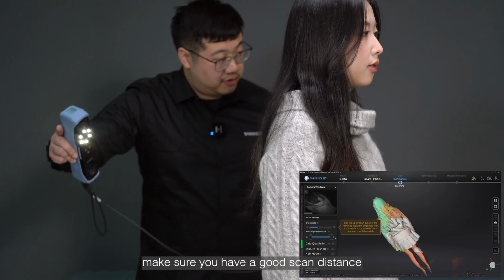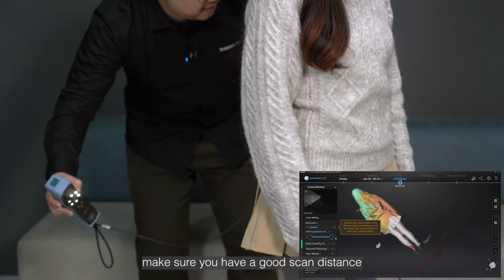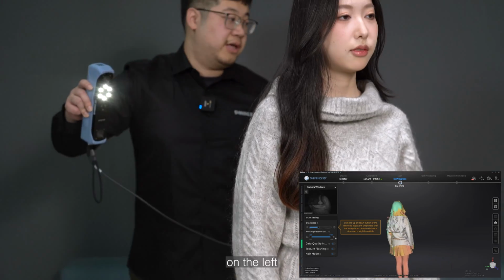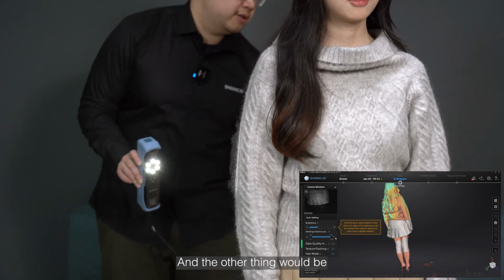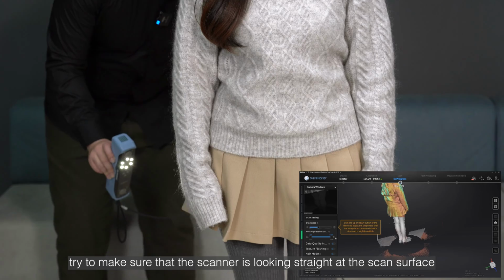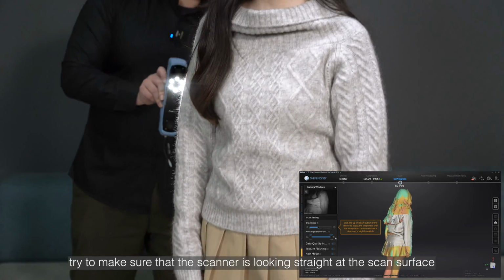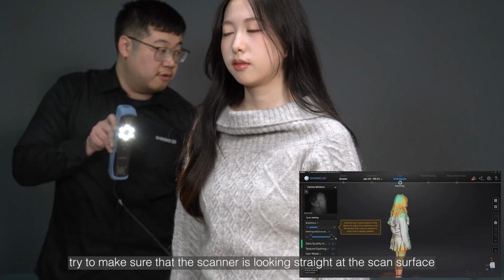During scanning, make sure you have a good scan distance. You can check the distance bar on the left. And the other thing would be to try to make sure that the scanner is looking straight at the scan surface.